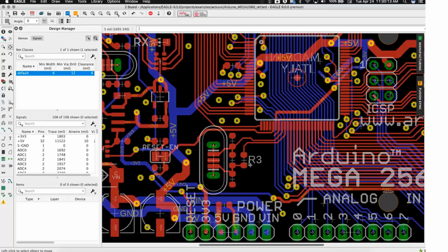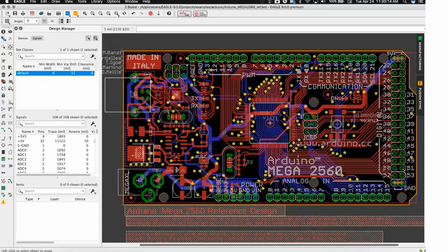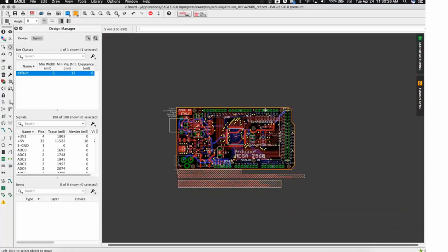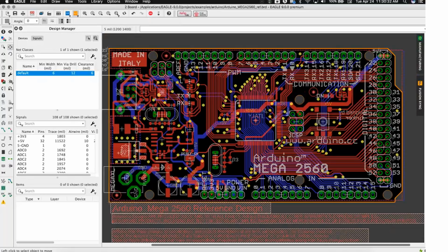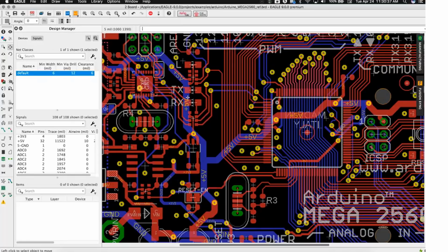That being said, that kind of brings us into the PCB environment. And I want to note one of the big standouts in PCB, which is the addition of the Design Manager panel. One of the things that we recognized was oftentimes you would load a board, you'd have a whole pile of components sitting out here. You'd have nets and air wires and tracks and all sorts of other content and resources that you were looking for inside of the design, and you needed some way to navigate it.